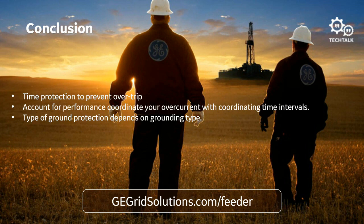So what I would suggest doing is there is a retrofit kit that's available to retrofit those SRs into an 8 series. There's a great video on that in our resources page. Whoever asked this question, I should send you a link to that. Basically, you take the terminal blocks off of your 750 case, and those terminal blocks will plug into your 8 series retrofit case.